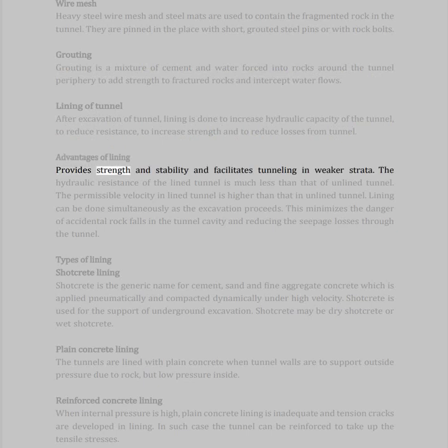Advantages of lining: provide strength and stability and facilitate tunneling in weaker strata. The hydraulic resistance of the lined tunnel is much less than that of an unlined tunnel. The permissible velocity in a lined tunnel is higher than that in an unlined tunnel. Lining can be done simultaneously as the excavation proceeds. This minimizes the danger of accidental rock falls in the tunnel cavity and reduces the seepage losses through the tunnel.